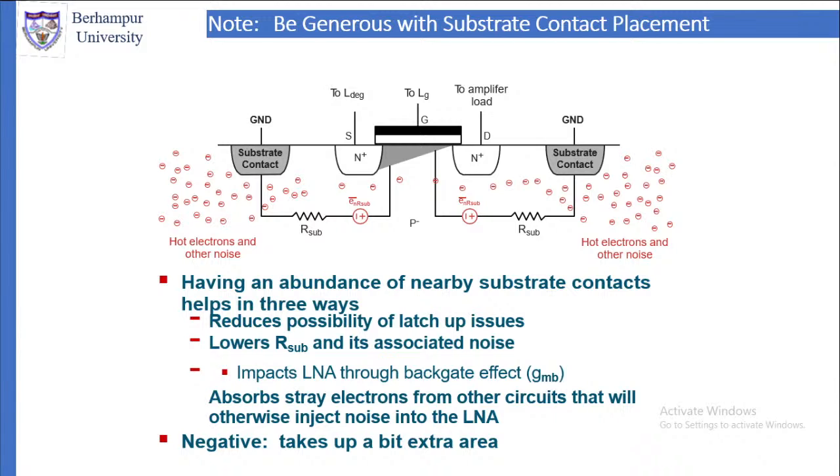Now, note that you should be generous with substrate contact placement when you are designing the device. Because if you do that, then having an abundance of nearby substrate contacts helps in three ways.